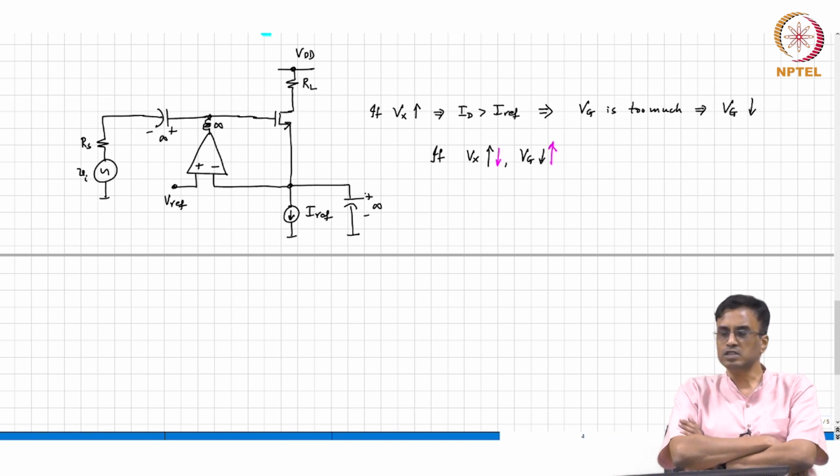Okay. And by the way, a common source amplifier is a transistor biased in saturation. In principle, it is just simply an incremental voltage controlled current source with some transconductance GM. And in principle, is there any limit to the amount of transconductance we can get? You have a transistor, right? And the GM, as you know, is square root of 2 mu n C ox W by L times I. So, in principle, is there any limit to the amount of transconductance you can get from a transistor?